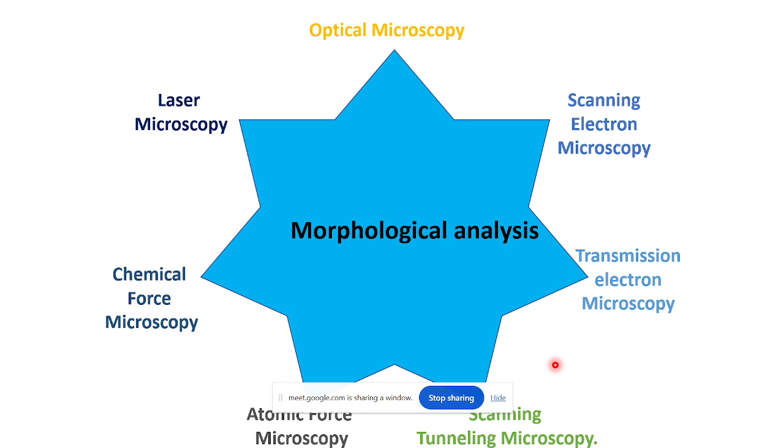So from SEM you may see, I don't know whether you have seen an SEM image or not. You can go up to 200, 300 nanometer. In that range, you can clearly see the distribution of different filler materials or the dispersion of filler material or other additives in your polymer matrix.